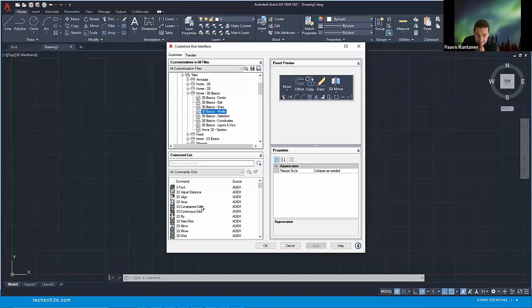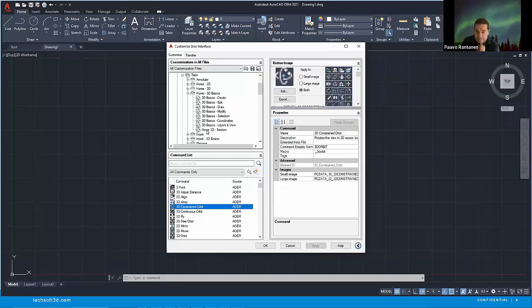You can add new commands, and you can add them to your ribbon items, and you can put help file topics, you can name it, you can assign icons, and you also refer to the actual command that you write in your C#, VB or Lisp or whatever it is. So this is a lot of manual work, and then you also need to design a lot of buttons and icons. We're not going to do that here.